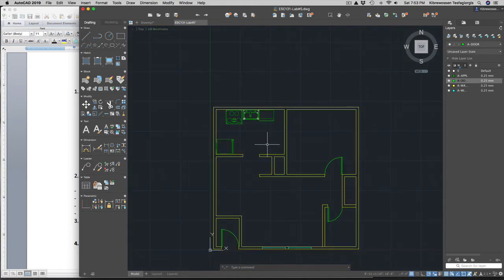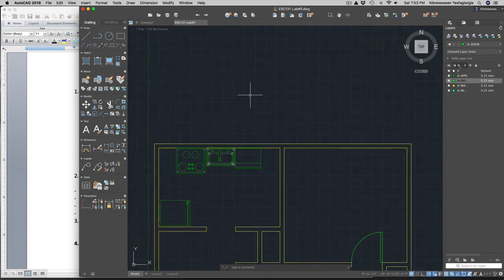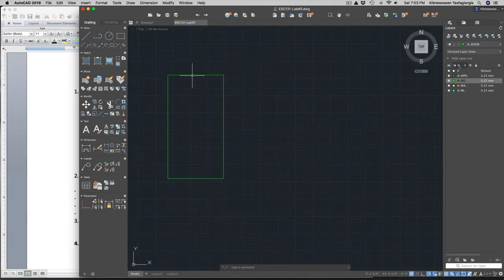The way we're going to proceed is you create your own toilet dimensions, but I'm going to draw one for you here. I'm going to draw a rectangle: 15 inches in this direction, then 8 inches in this direction, and again 15 inches in this direction, and I'm going to close it. So I have a rectangle that's the back of the toilet seat. Then I'm going to fillet.